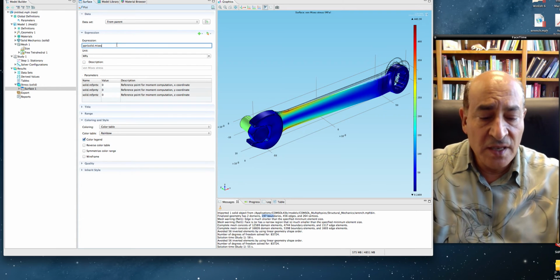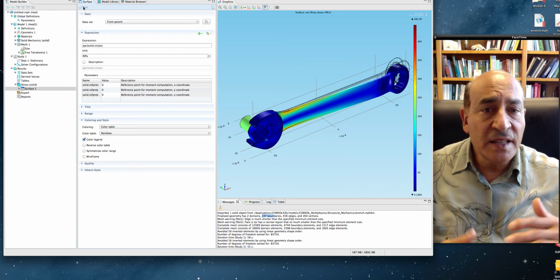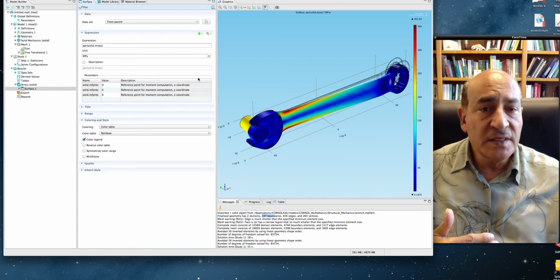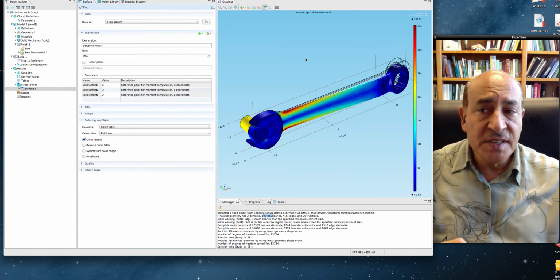It works on Mises and filters it, and then it does a recalculation. You can see now it gave us a different, smoother profile, and the maximum is 352 instead of 430. This is much more reliable, so we can actually design on that particular maximum.